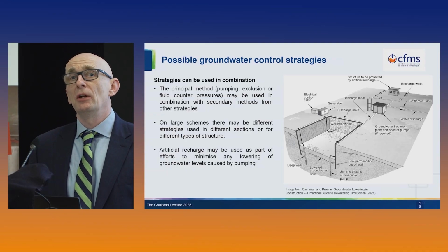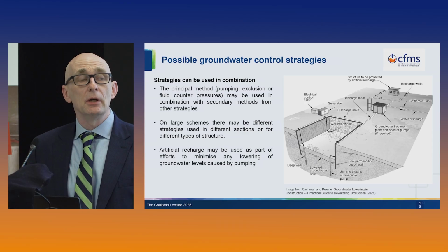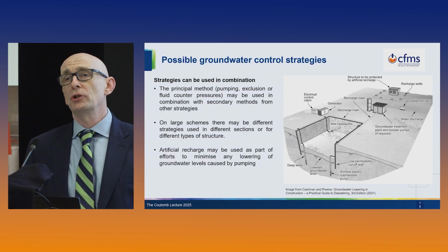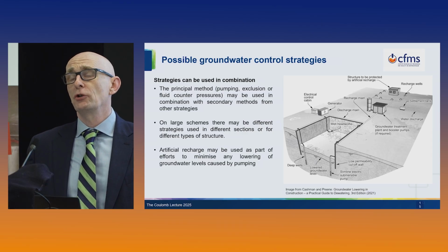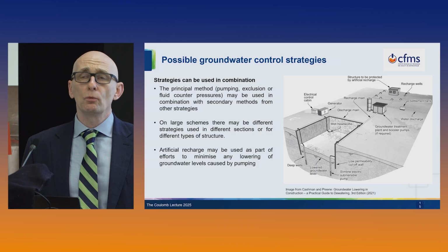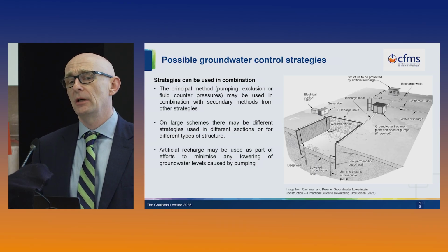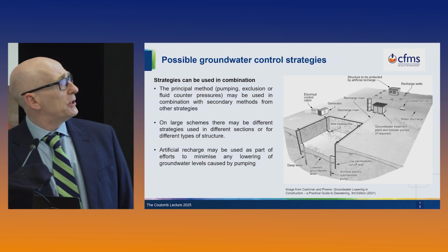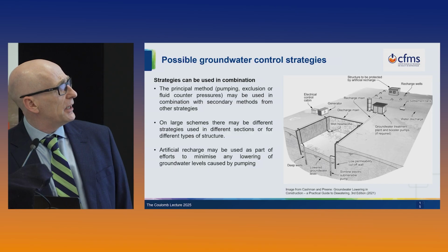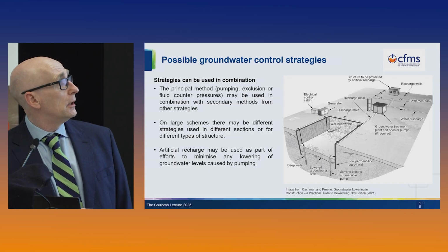I've described 3 different strategies, but it's important to realise that these strategies can be used in combination, either on one single structure, or maybe if you have a large or a long project, you might use one strategy in one area and a different strategy in the other. This image here shows an excavation that has a perimeter cut-off wall, which is essentially an exclusion approach, but there's some significant pumping going on here from deep wells.